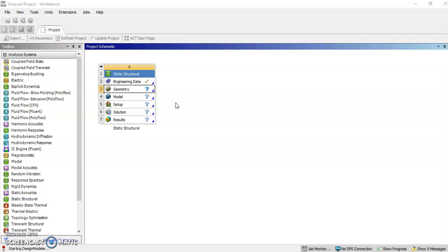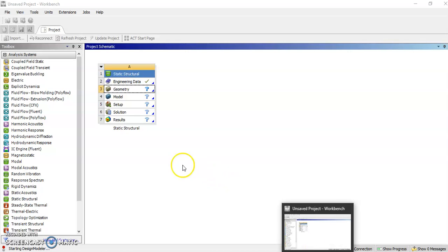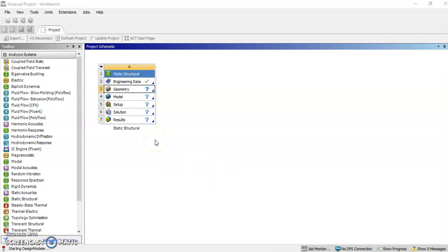Okay, so it takes some time because the geometry window is new. Once we have followed the step in this third category, that is, we right click on geometry and choose the option of the new design modeler for drawing the geometry. It takes some time for opening the window, just a minute. It will take a few seconds for opening that new tab where we can start to draw the geometry, that is, creating the line and assigning the cross section for that line.